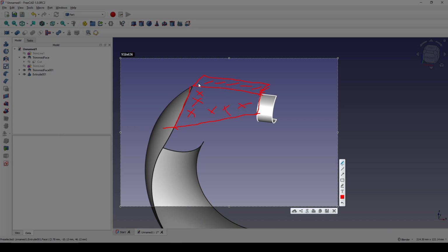Okay, here is the G1 continuity, and here also G1 continuity. But because this edge has no face support to it, I cannot use this big surface. So I just want to use a small area in here. Okay, a small area in here. So after I'm done with that, I will have the first piece.